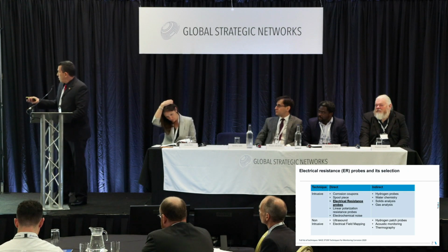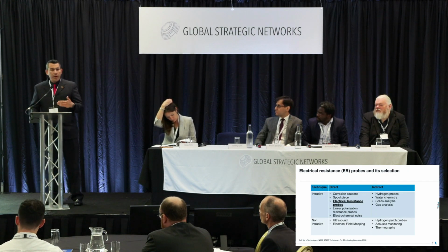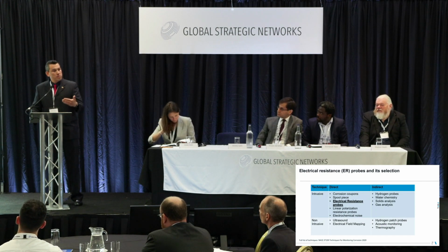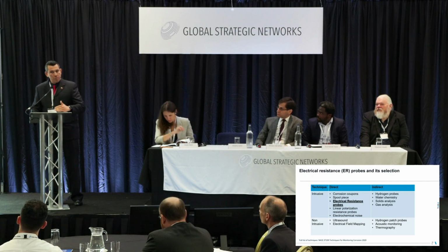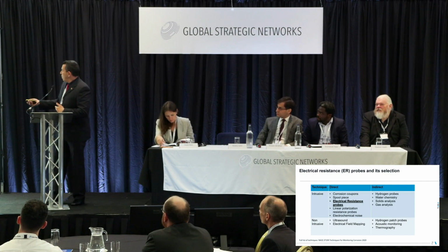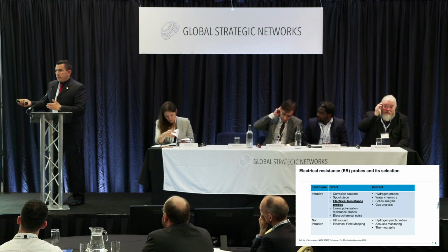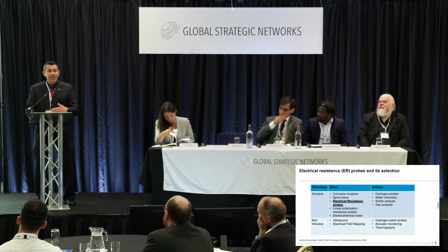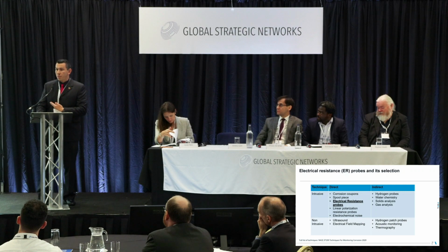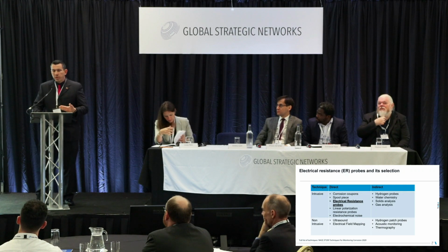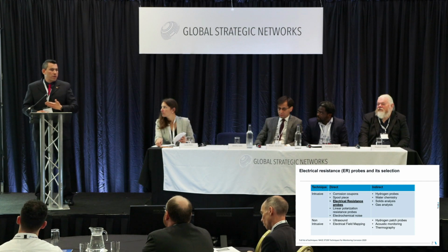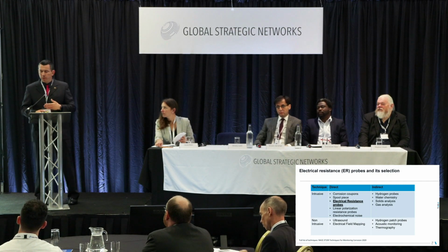water chemistry. When we check water chemistry, we can read the pH. Definitely pH will have an impact on the corrosion rate. Usually, the lower the pH, the higher the corrosion rate. Another example of indirect monitoring is iron count, because the higher the corrosion, the higher the iron count will be in our water chemistry. So if we don't have the possibility to install corrosion coupons or corrosion probes, because maybe we have limitations to install access fittings, at least indirect techniques can give us some information.